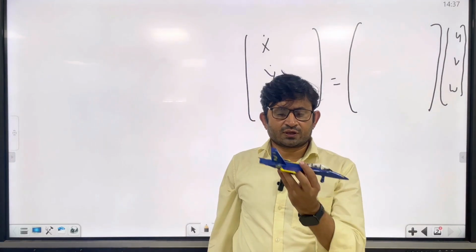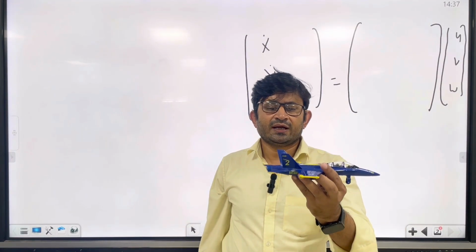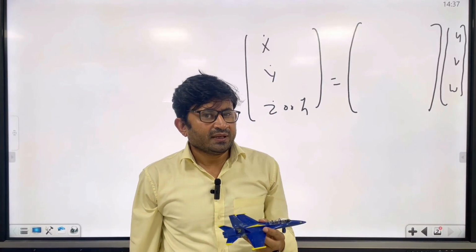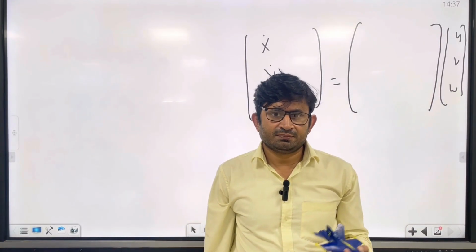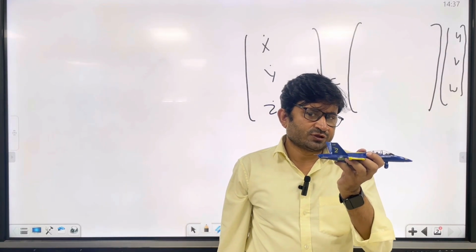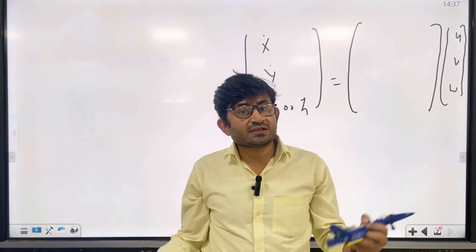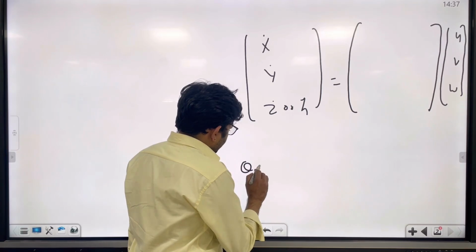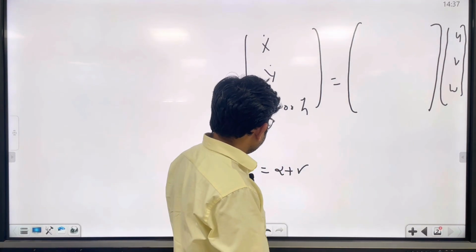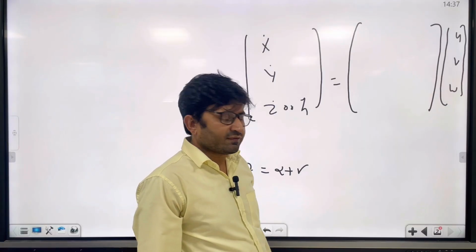Here, let's say if you are controlling the altitude, so you are not moving laterally, and also you can approximate it as a small angle of flight, and since the aircraft is not changing the altitude, angle of attack is also small, from theta equal to alpha plus gamma. Gamma is the flight path angle, right? Gamma is 0 in steady state level flight.